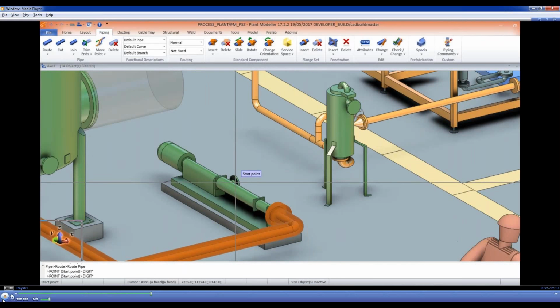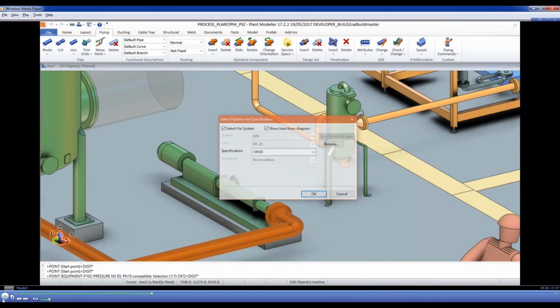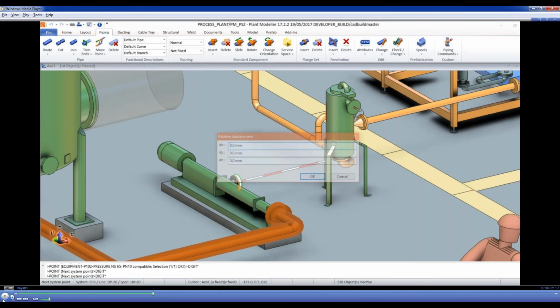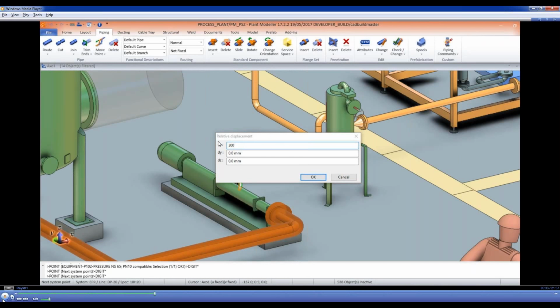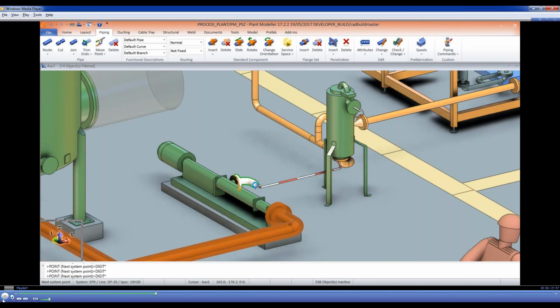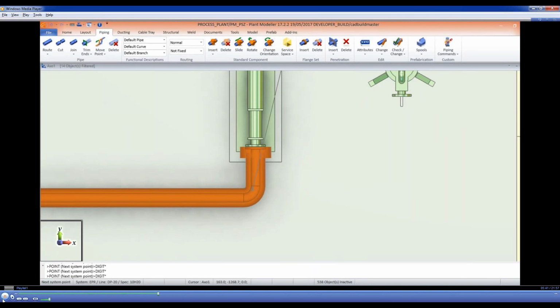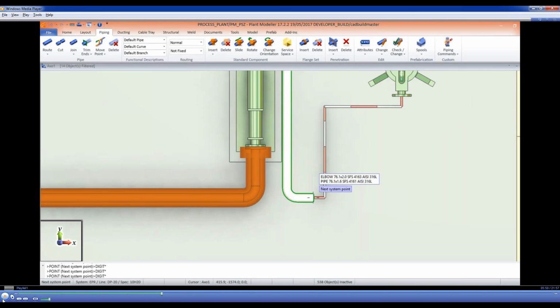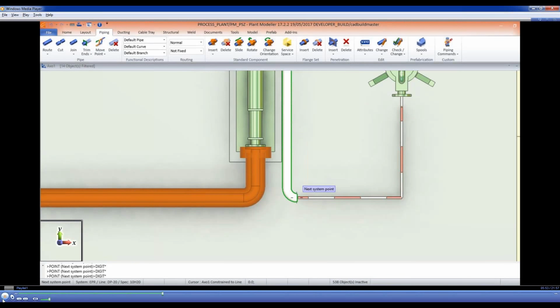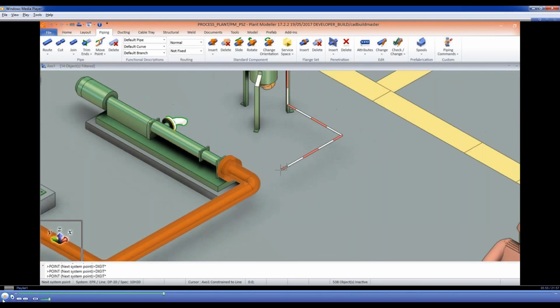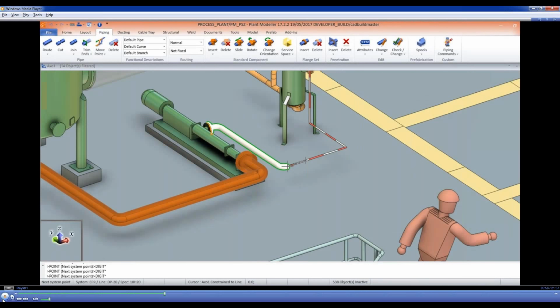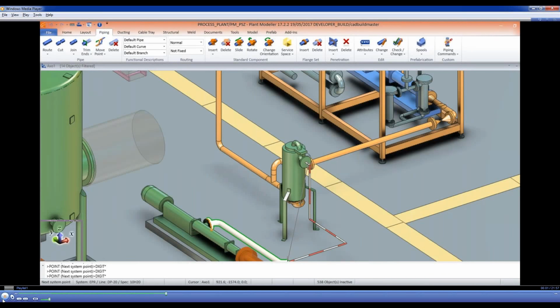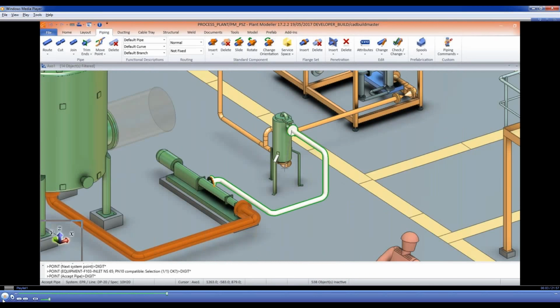Parts to the pipe are coming according to the specification, so if there is a flange connection, a flange will be added. And now this pressure side pipe is routed to the end. I will use once again some reference points to head to the filter, picking a point from this elbow. Then we will point to the X direction, and let's see, we have to head to the filter. The rest of this will be just automatic routing by selecting where to go, and there it is.